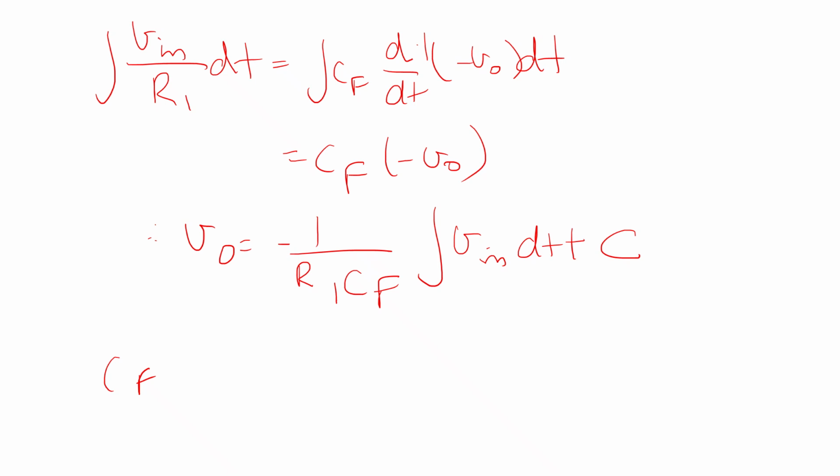Across the feedback capacitor, so the stability can be obtained. The frequency is given by f is equal to 1 by 2 pi R1 CF. Both the stability and the low frequency roll-off problems can be corrected by the addition of a resistor RF. In the feedback path we had connected a capacitor.